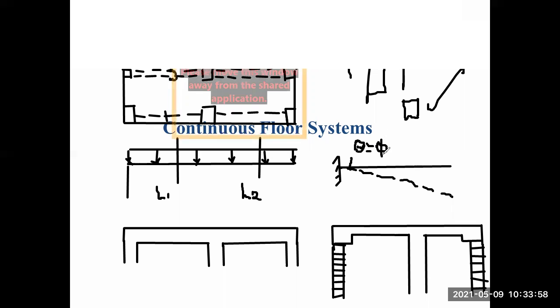But for a simply supported beam, with the ends, if this is the end, the other side, and this is a hinge. Do we have any restraint at the ends? You see, it deforms this way. Do we have moment at the end? Do we have moment?